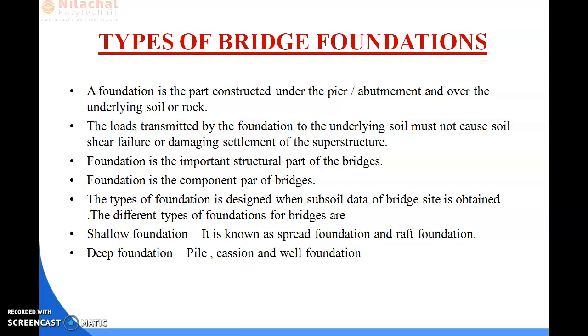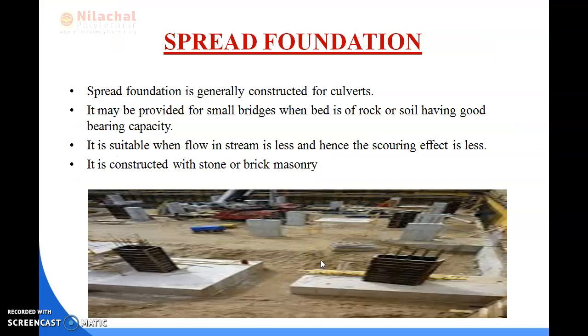Okay. And basically the type of foundation is designed when the subsoil data of the bridge site is obtained, and the different types of foundations for the bridge are given, that is your shallow foundation and deep foundation. Okay. Shallow foundations are known as spread foundation and raft foundation, and deep foundations are pile, caisson and well foundation. Okay. So first we discuss what is your spread foundation.